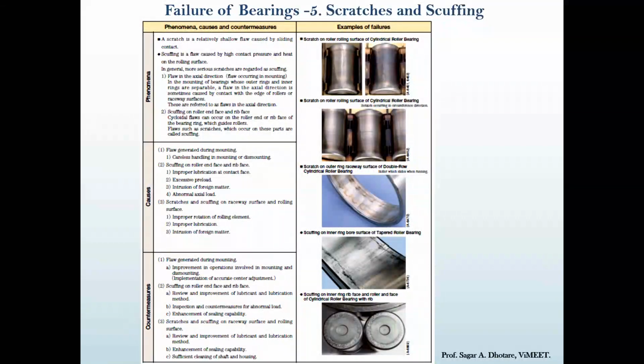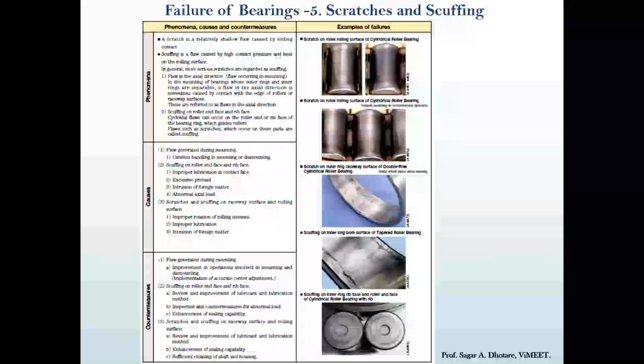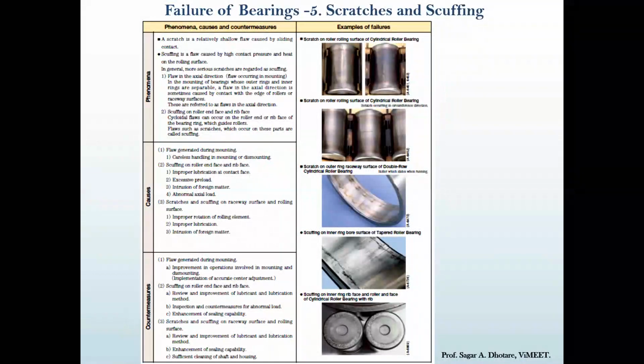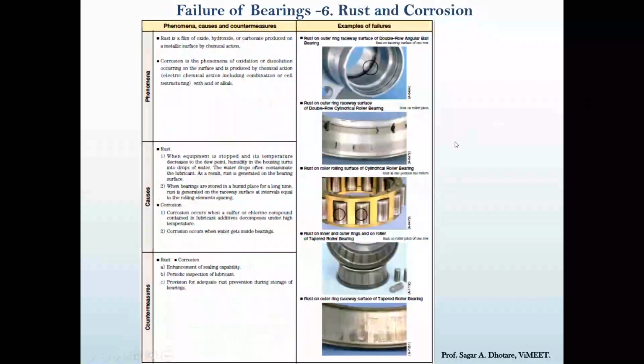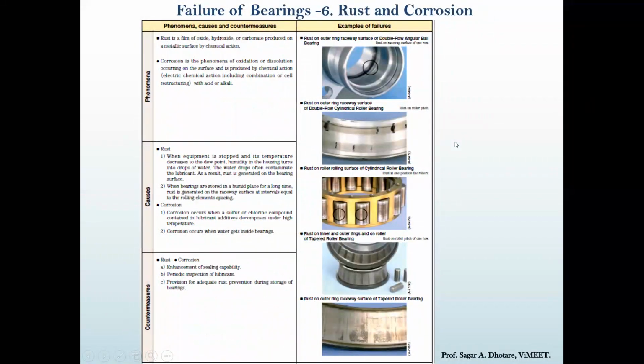Scratches occur because of improper rotation of the rotating element, as usual improper lubrication, and because of foreign particles which can be inside the bearing.